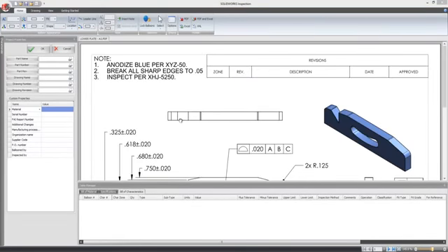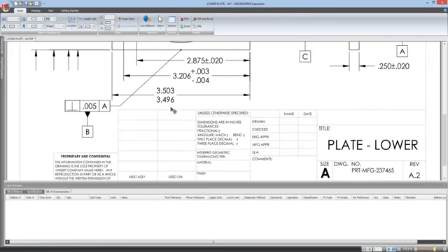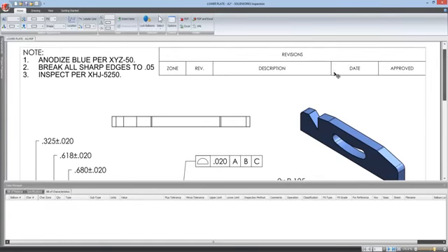So it can be used by somebody who hasn't got SolidWorks on the machine, this standalone application, and it doesn't even need a SolidWorks drawing for it to function quite nicely. So within here we'd start to capture some information about the drawing for our project, so things like the part name. We'll grab that using the inbuilt OCR tool, so we just window round an object and it should pick up the text information. Maybe we want to capture the revision as well, so we'll just drag around that like so. Once we've captured that information, we can say OK, and we can start to work our way around the